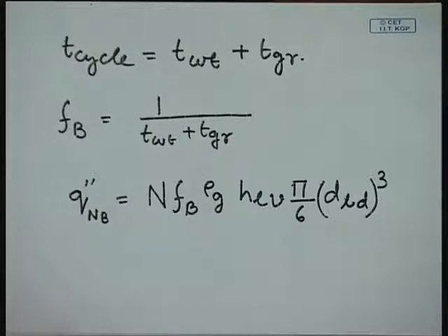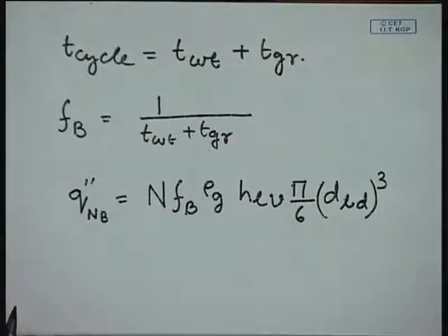Because N is a surface characteristic which comes from many things: the process by which the surface has been manufactured, the contamination the surface has gone through, that means the amount of oxidation and fouling that has taken place on the surface, and of course the number of activation sites also depends on temperature, as I described in our last class.